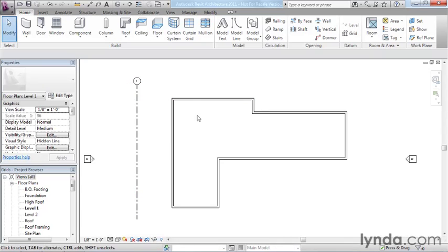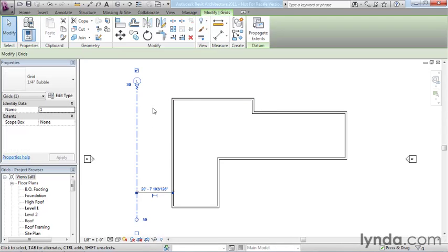And one of the reasons that I drew this grid off to the side was to kind of point out some of the controls similar to what we had in Levels. In the Levels movie, we have the little open circles that we can use to change the length of the level. And talking about the bubbles, we have these little check boxes. Now, the little check boxes actually appear in Levels as well, so you can do the same trick there. If we want a bubble to appear at the bottom, we can simply check the box and it will show a bubble. Likewise, if we want to hide a bubble that we previously showed, we can check the box and it will hide the bubble. So if you want them at both ends, you can have them at both ends or at either end.